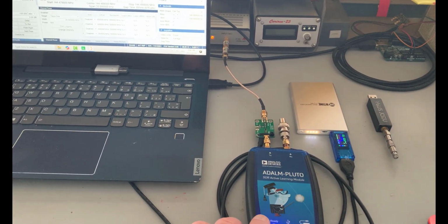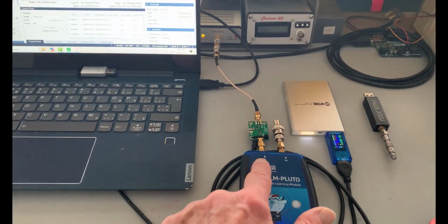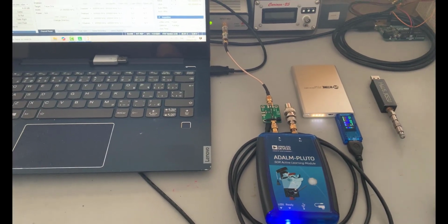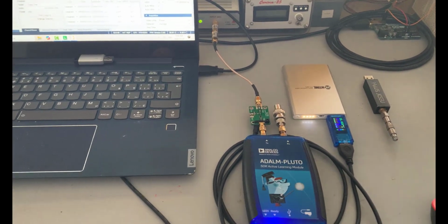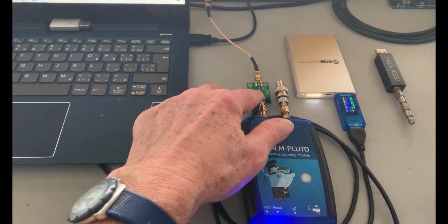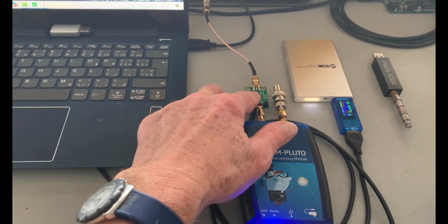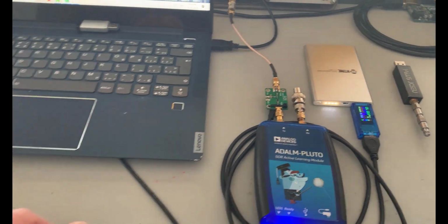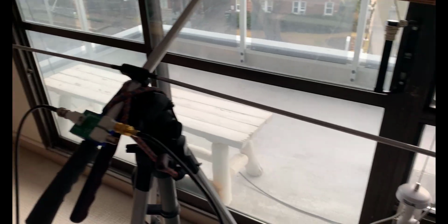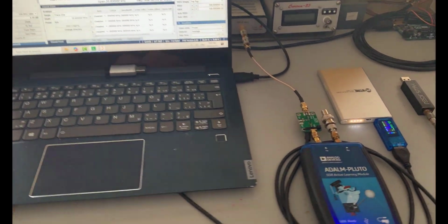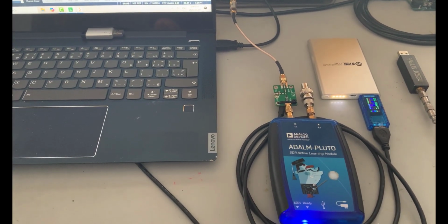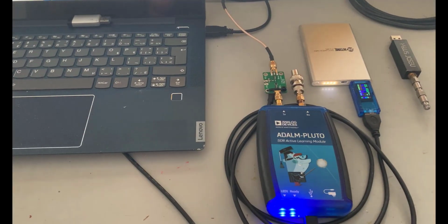And if you consider the power of the Pluto, at the TX port here, it's only about 0 dBm. But since I looked at this 3 years ago, I've got two sets of extra equipment that have appeared on the scene. This is a 20 dB LNA, which I used with my CubeSat. It's a wideband LNA. I've also got this 2 meter 70 centimeter Yagi. So I thought, let's give it a try and actually do a test with the Whisper Beacon on air using the LNA and the Yagi, so I might have a chance of actually getting out there.